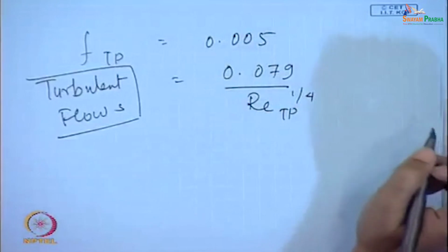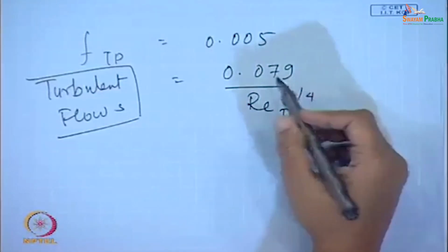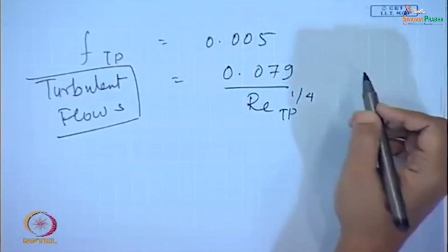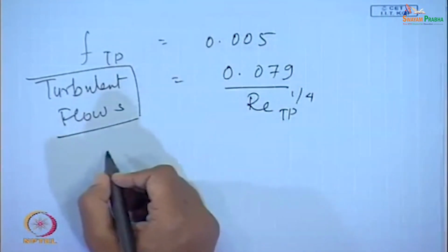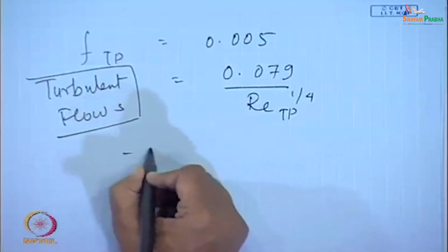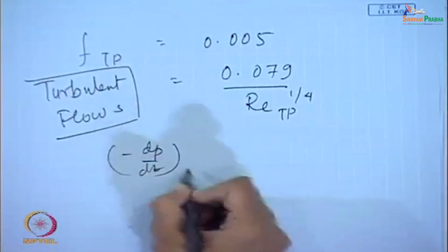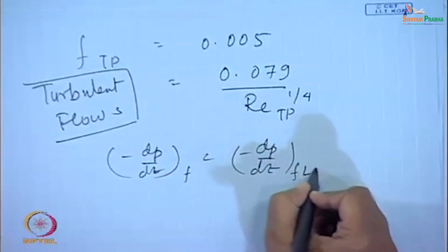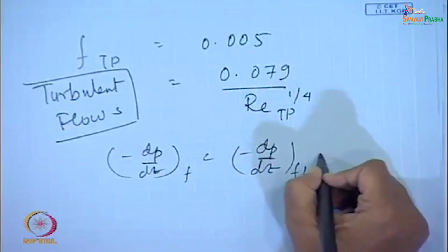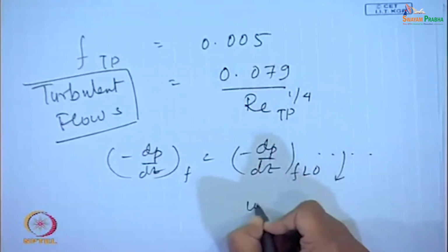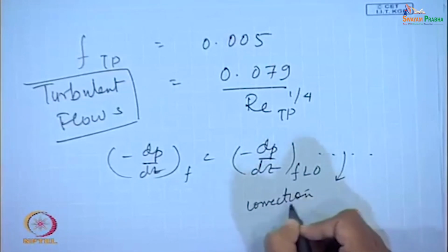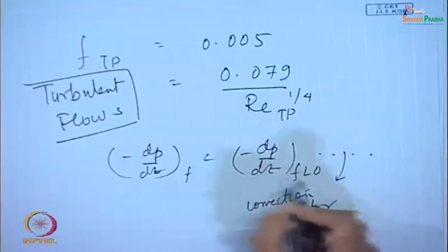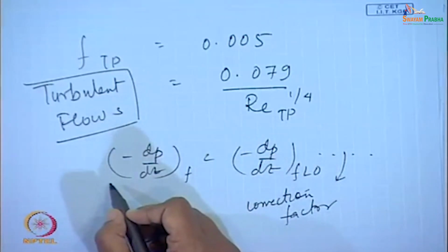Any of them we can take and accordingly substitute it, and if we proceed, then in a similar way you will be in a position to express the frictional pressure gradient as the frictional pressure gradient for liquid flow only, and some sort of a correction or modification term which needs to be added to the single phase pressure gradient in order to obtain the two phase pressure gradient.